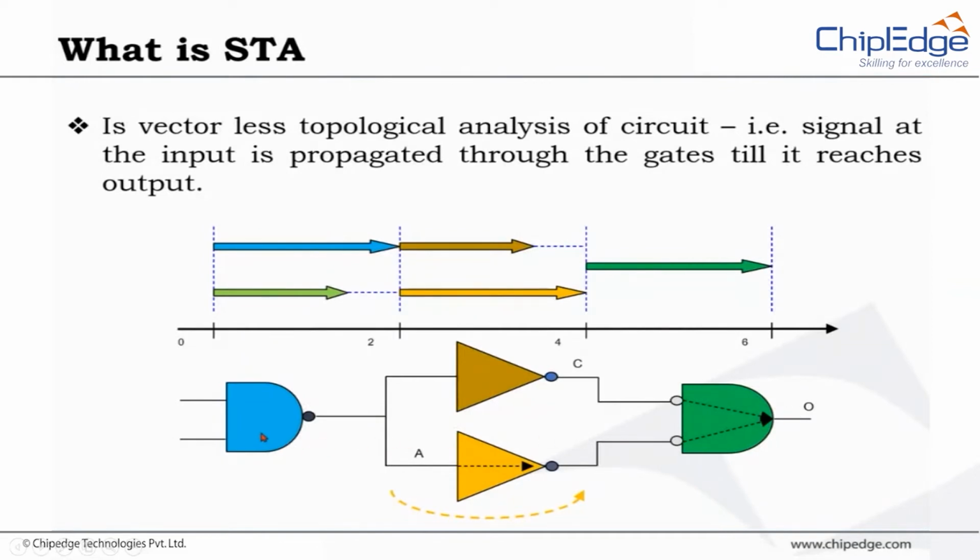Static timing analysis has the ability to look through all the possible paths in your design like this. And it comes up with what is the worst case path between point A to point B. So that's what makes this tool exhaustive, because it has the ability to look through all the possible paths. Now, as opposed to, let us say you're trying to run a simulation, your simulation may actually toggle just this vector, this point. It may not be toggling this point at all. So you're limited by the ability of your simulation to toggle a node to see what is the variation because of that variation in delay.